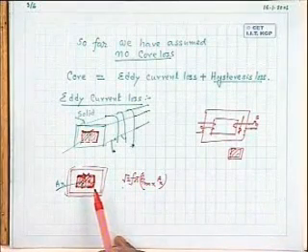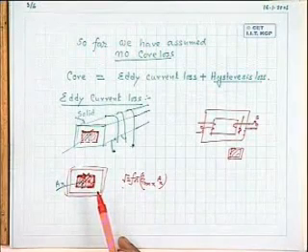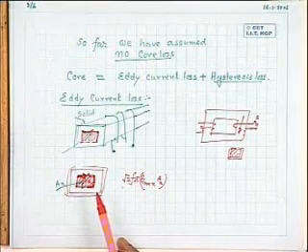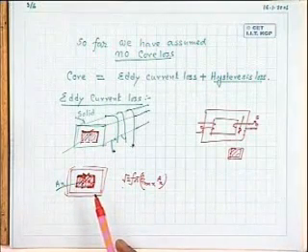And not only that, the moment this carries current, it tries to disturb the flux inside the core, which in any case the primary will try to counteract. How will the primary react to this one? It will draw some extra current to compensate for this extra MMF, which tries to disturb the level of the flux.